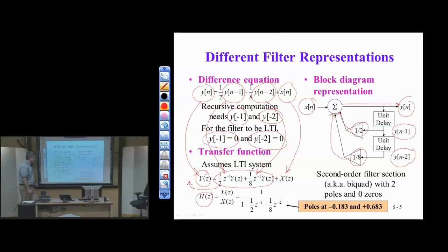Okay, so anyways, this is a biquad. We call this an all-pole filter. That is to say we have only poles that are of interest. Yes, we have 2 trivial zeros. Those are not terribly interesting, but anyway, this is an all-pole filter with 2 poles and 0 zeros that matter. We'll need this on the next slide. Okay, so this is an example of a feedback, second-order system.